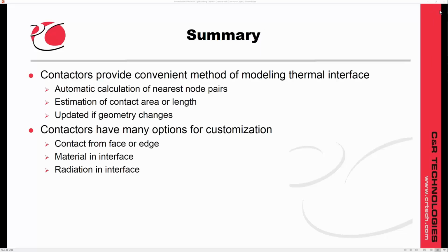Okay, well that's the end of the presentation. In summary, the contactors provide a very convenient method of modeling thermal interfaces. There is automatic calculation of nearest node pairs and estimation of contact area or length, and it's automatically updated if your geometry changes. There are many options for customization, including connecting from faces or edges, putting material in the interface, using radiation in the interface. So there's a lot of possibilities here with the contactors.